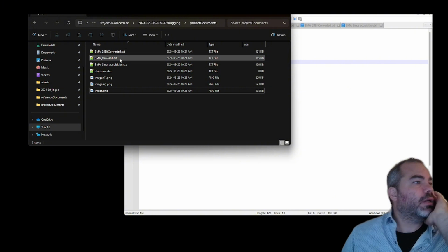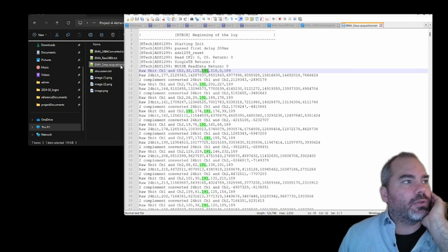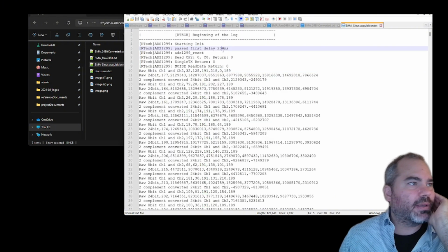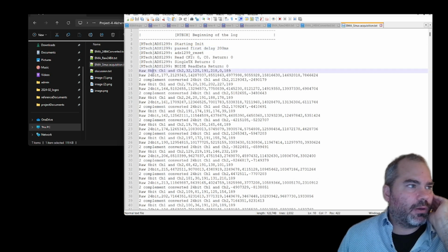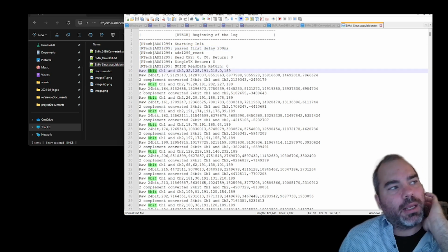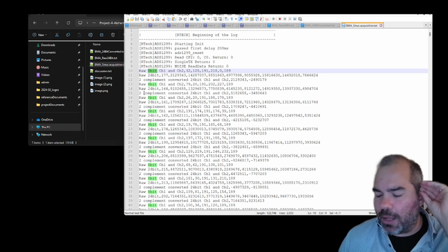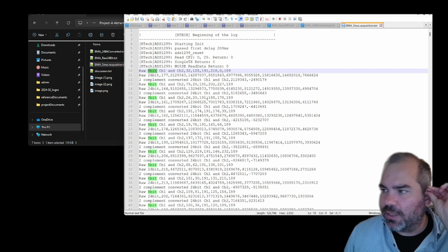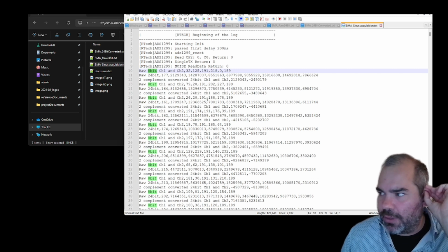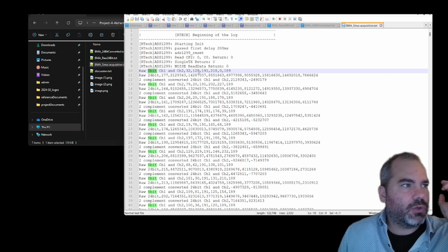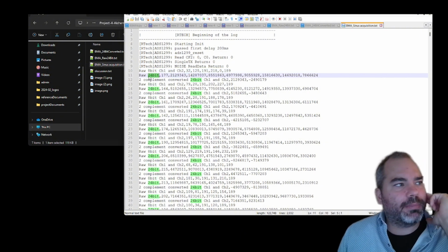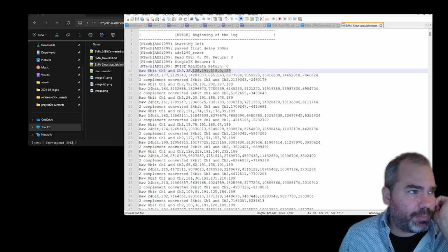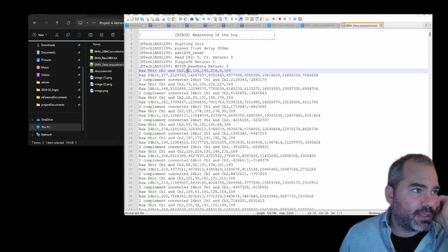Just show you here. So I will have to look into it. This one seems to be the most complete. I have 8-bit. Okay, so the ADS1299 outputs signals on 24 bits, integers. So we break it down in 8 bits. And then here's the assembly in 24 bits. So there could actually be an issue with the way that these elements are assembled.